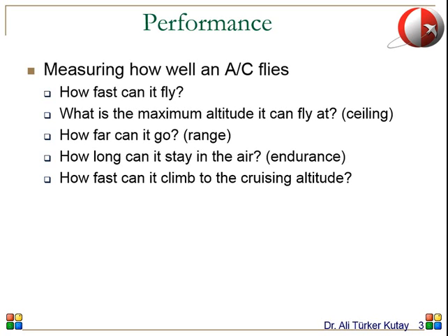There are some noise regulations. Especially when taking off from an airport close to a city, you need to climb as quickly as you can so that you will be above the city. Obviously, for military aircraft, it's important as well. If there's a threat that can attack your aircraft, you want to climb as quickly as you can so that you'll be out of the range of enemy fire.